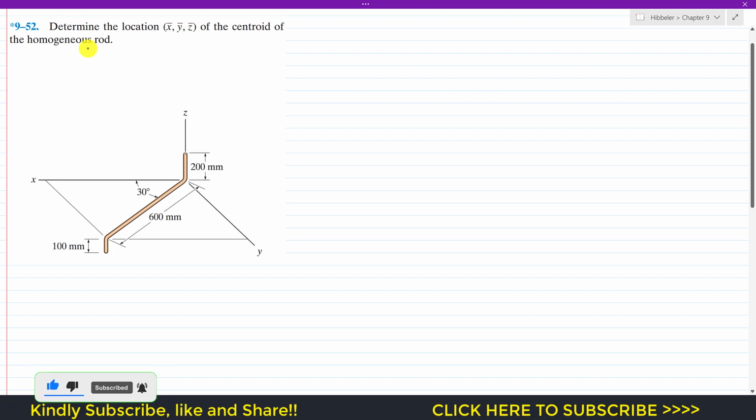Now we are going to solve this problem which says to determine the location of the centroid of this homogeneous rod. So we have to find x bar, y bar and z bar of the centroid of this homogeneous bar. As we know, x bar is equal to the summation of x tilde times L divided by the summation of the length, that is the total length of this homogeneous rod.